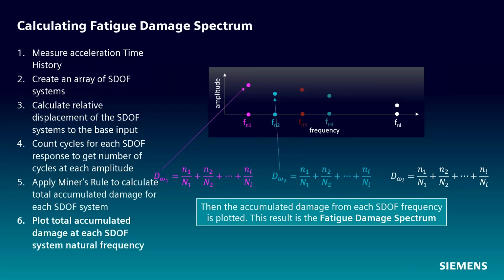and then connect the dots. And this is our fatigue damage spectrum. So a different amount of damage per frequency. I guess that's good if we have certain resonances or whatever in the environment to be able to vary that. Yeah, we could take a look at our test article and understand where critical frequencies are and try to figure out a way to either move those frequencies to a less damaging area of the curve, or design some stowage procedures or some packaging that's going to protect our DUT from these damage cycles.